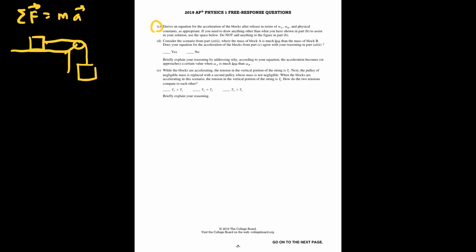The way I would typically think about this is to draw in all of the forces that point along the direction of this green arrow, and write one Newton's second law equation for that. Any force that points in the direction of the green arrow, I'm going to call positive, and any force that opposes it, I'm going to call negative.